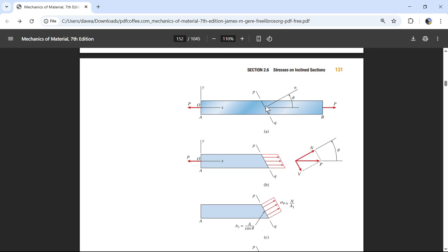And it can take a compressive stress in psi. You know what I mean? Putting forces on either side, compressing some sort of area, you're going to get a compressive stress of 58,000 psi. But it can only take a shear stress of basically half. If you're on the safe side, you use half. It can be as high as 60% or 65%, but it can only take a psi of half in shear.